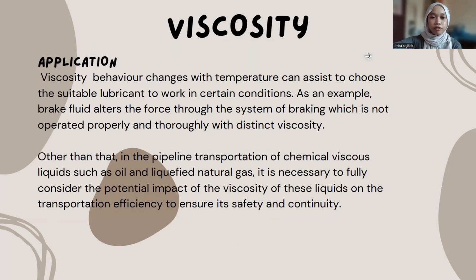So first, we have viscosity. A simple definition for viscosity is a measure of a fluid's resistance to flow. For its application, viscosity behavior changes with temperature, which can assist in choosing the suitable lubricant to work in certain conditions. As an example, brake fluid transmits force through the braking system, which does not operate properly and thoroughly with a distinct viscosity.